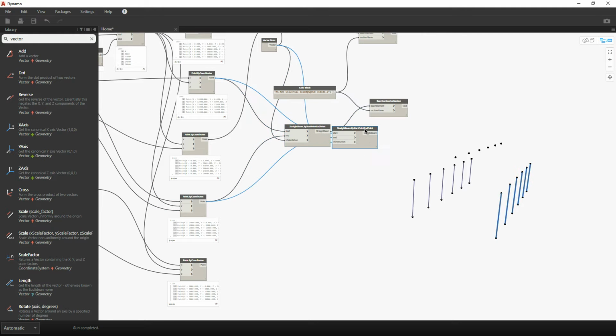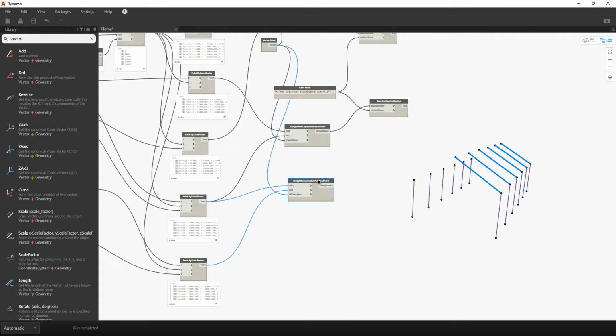I'm going to copy that function again, just get rid of those, and I want to connect this point to our roof. There's one side, and again, same thing, I'm going to do the beam set section, connect this element instead. I'm just going to keep that one beam, that one code block, just because it makes it easier for this.